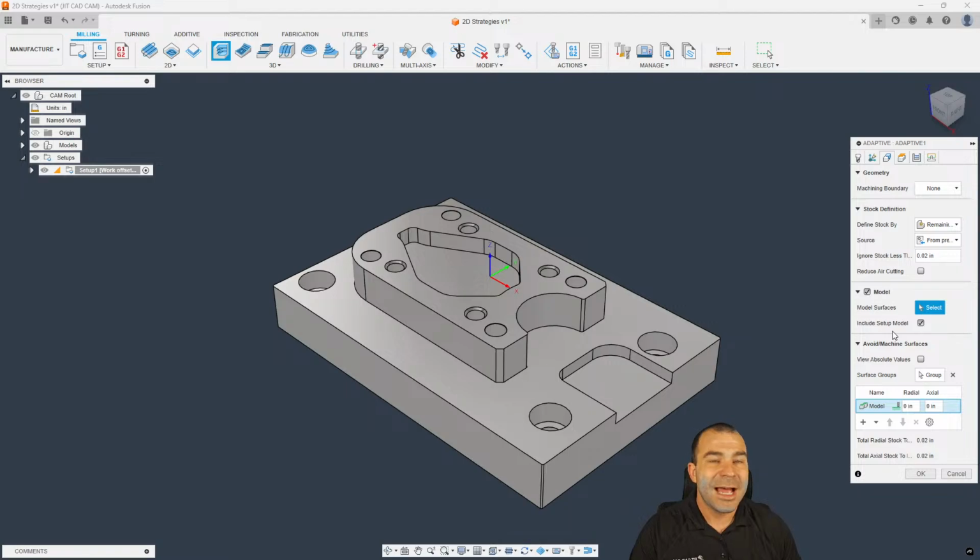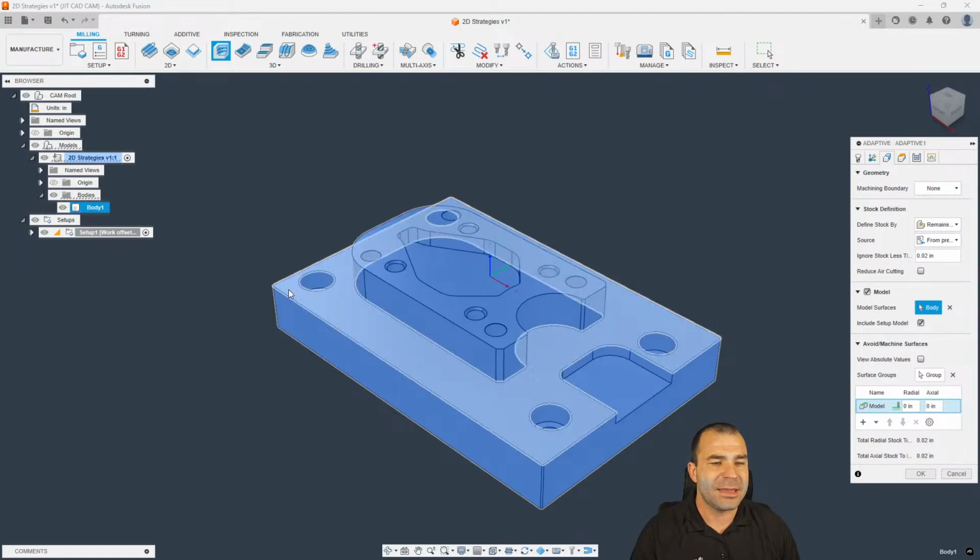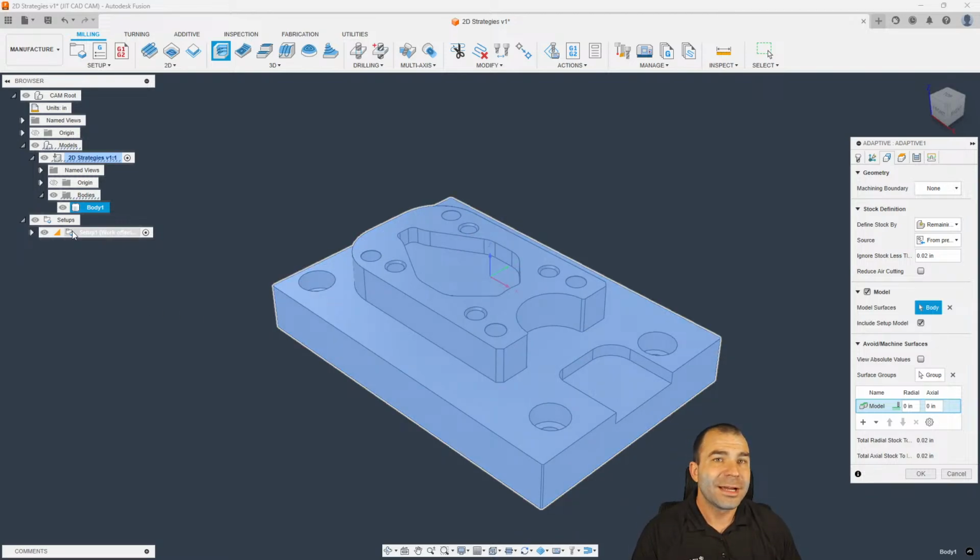But as you're going to see, I don't know why people always, when they first start in Fusion, think they have to do more than they do. If you've ever seen any of my videos, I always tell people just hit OK. But I commonly see people come in and redefine the same model more than once, right? They think, oh, well, I need to define the model here at the toolpath level. However, you've already defined that at the actual upper setup level. I would refer to that as your world coordinates, if you're familiar with that, or a kind of global setting for a lot of your toolpaths. That would be where our model sits at our setup.